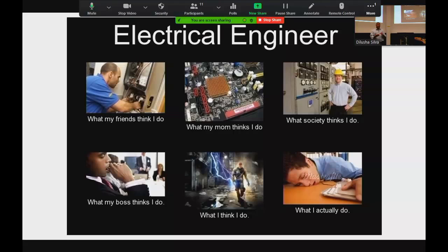What we tend to do is first look at the load, understand the characteristics of the load. So is it a machine, is it a motor, or is it just another switchboard with final circuits on? Right. Then we look at the environment it's going in, and then we go, I haven't installed fuses for 20 years, let's not do that ever again.